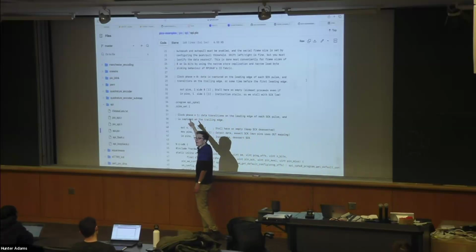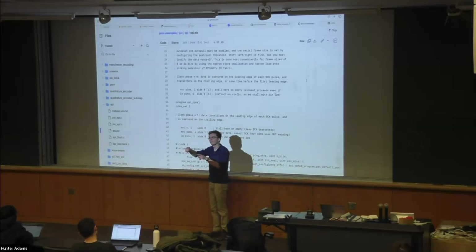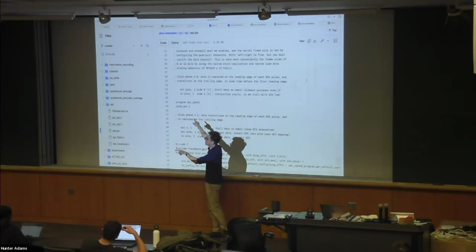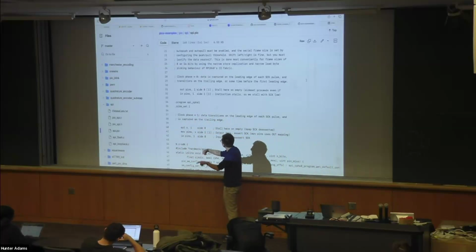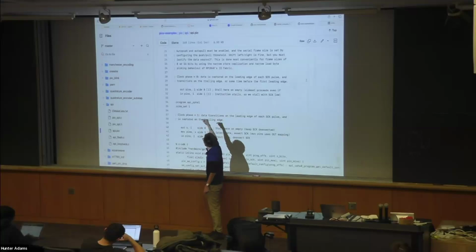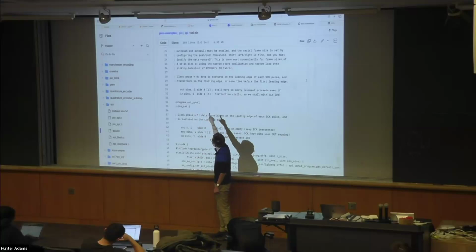We will have a different pin mapped to the in instruction. So the in instruction will be talking to one of the GPIOs. The out instruction talks to another GPIO. So the out instruction is talking to our MOSI line, our main out, secondary in. The in instruction is listening on the MISO line, the main in, secondary out. We pull 1 bit off our input pins and simultaneously toggle the clock from low to high.